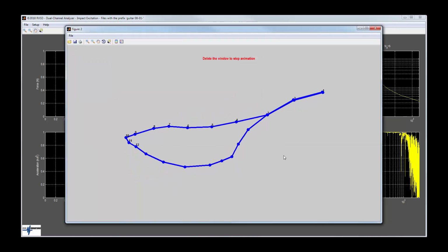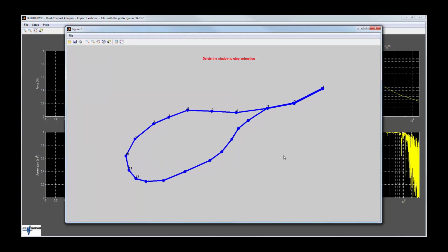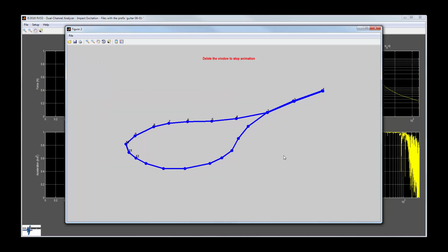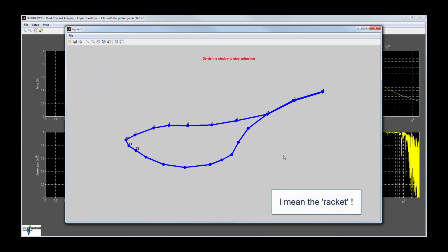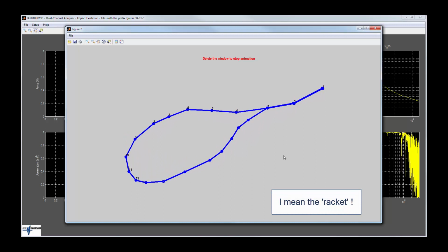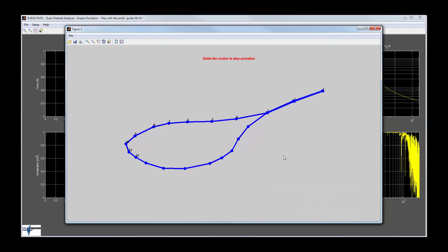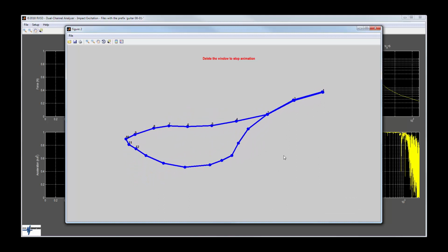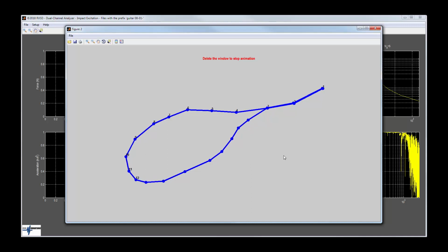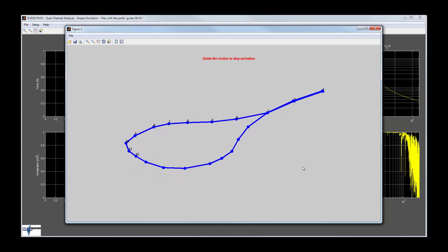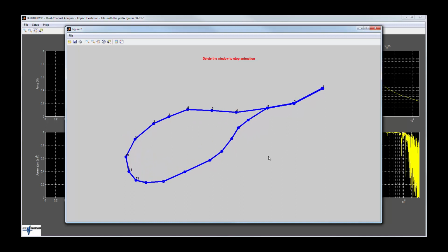This looks like a second mode of the guitar. This technique, for two-dimensional objects only, is to take a photograph of the object in the right plane, and then use these nodal points to capture the FRF data. By tagging the FRF data to the correct nodal point, we can then generate the mode shape animation as you see here.